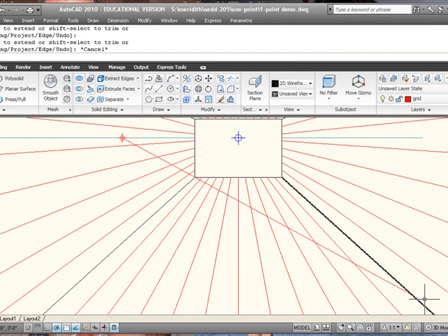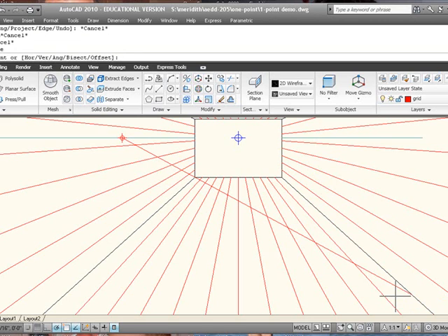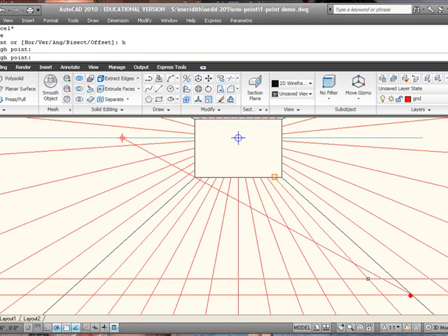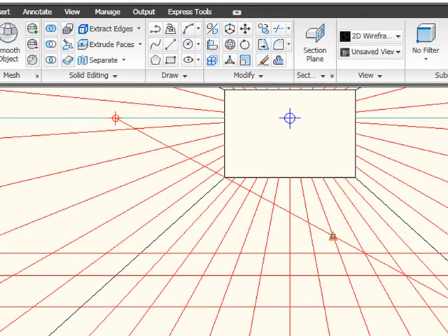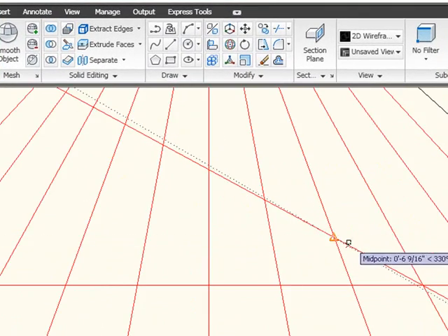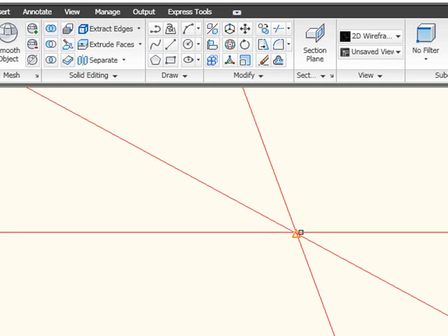Now what I'm going to do is draw a line, or let's use an X line in this case. I want to draw a horizontal X line, and I want it to go through this point, this point, this point. Notice that I'm putting a horizontal line everywhere that I happen to be intersecting. We want to make sure we get the intersection symbol.